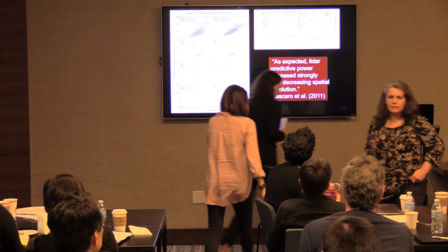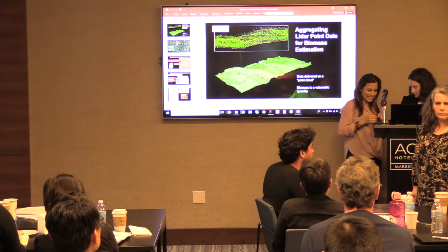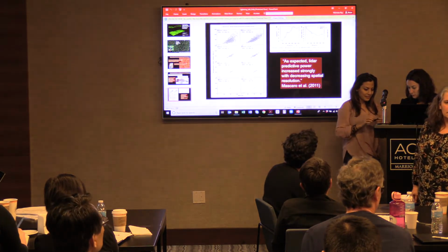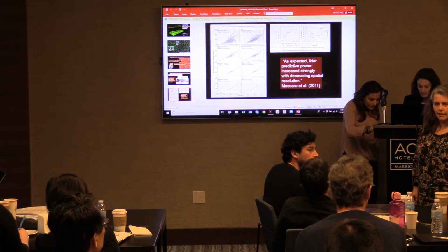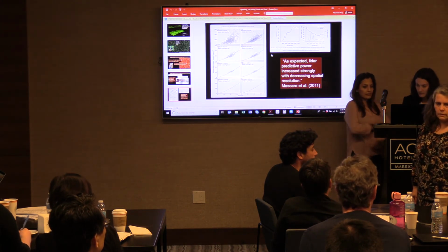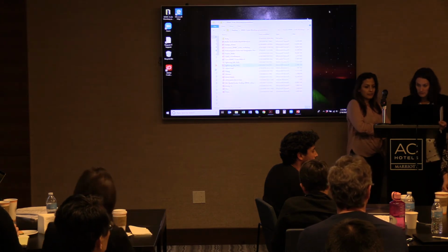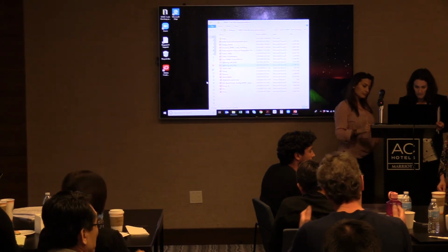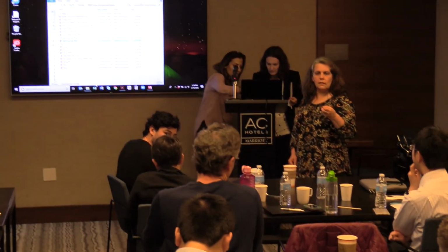Usually when we're looking at density, we're interested in points per square meter for the LiDAR, as well as whether you're getting first or second returns. Multiple returns give you an indication of the density of the canopy. And also with that high a density that we can get now, 50 points per square meter, you can actually look at the morphology of individual trees. Just wondering if you played around with that.